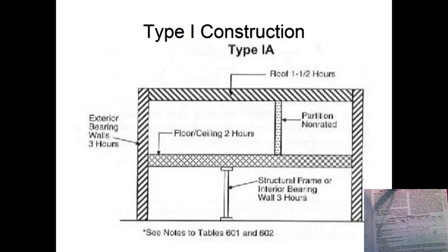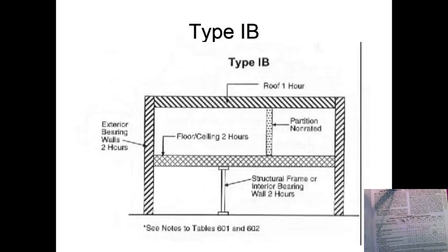So C, in all occupancies, heavy timber should be allowed where a 1-hour or less fire resistance rating is required. If it's less than 1 hour, and we had 20-foot ceilings, you could use, of course, the heavy timbers. If you're looking at 1B, this is showing you how that works. Bearing walls exterior is 2. So you see the 2 hours right there.